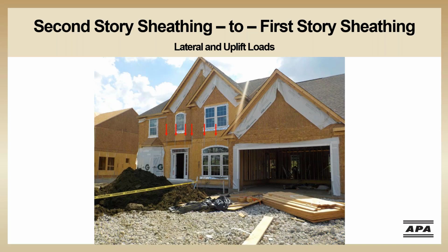Metal strapping only transfers uplift loads. It does not transfer lateral loads. Lateral loads can still be transferred by attaching the sheathing to common framing members. If this is not sufficient, additional hardware can be used that is designed to transfer lateral loads.